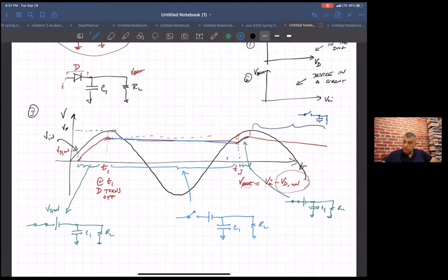So what happens is, once you get started, every cycle for a brief period of time the diode sort of wakes up because the conditions are there for it to turn back on. It dumps a bunch of current into the capacitor to charge it up. Because you have the load in parallel with the capacitor, momentarily you're also providing current to the load, but typically most of your current is going to charge up the capacitor.